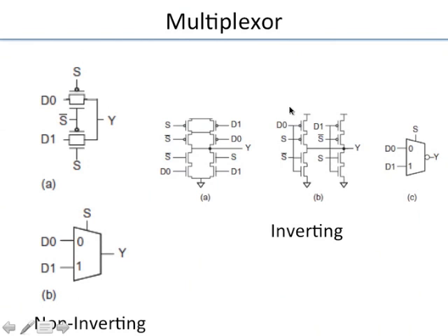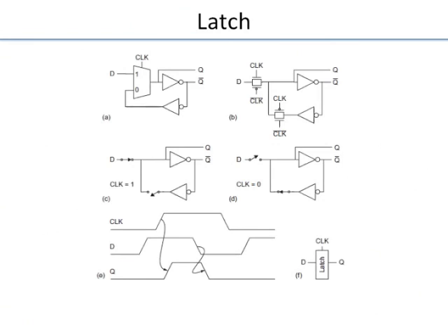So we have seen logic gates now. We have seen how to build compound gates. So we know how to build the computing engine, right? The computing engine, whatever logic you want to implement, adder, subtractor, whatever it is, decoding, all using logic gates. Now we know how to build it. Okay, so let us look at the sequencing elements. First we'll start with the latch. Typically most synchronous designs use flops, but a flop is built out of a latch. So first let's look at a latch.